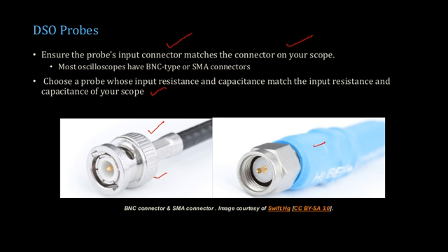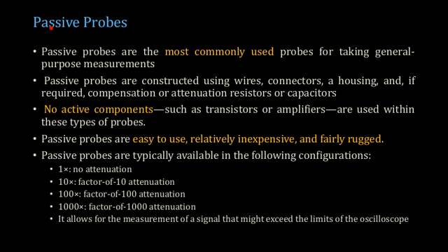If impedance matching is not there, that can lead to loading and such effects. Now there are a few types of probes which we are discussing: passive, active, differential as well as current probes. So the first one is the passive probe.